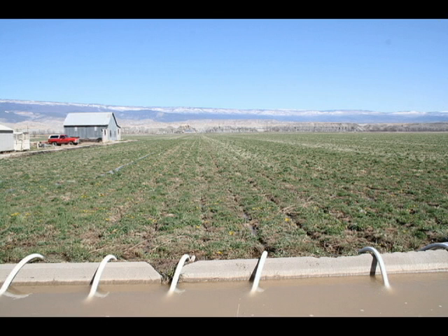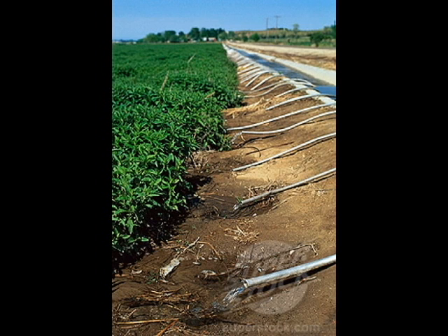The small tubes usually are used for furrow irrigation, although a number of them may be used together for border or contour ditch irrigation. For furrow irrigation, the tube sizes usually are selected so that 2 or 3 tubes per furrow will deliver the maximum stream recommended for the slope being irrigated. After the water has crossed the field, 1 tube is removed to provide the cutback stream.